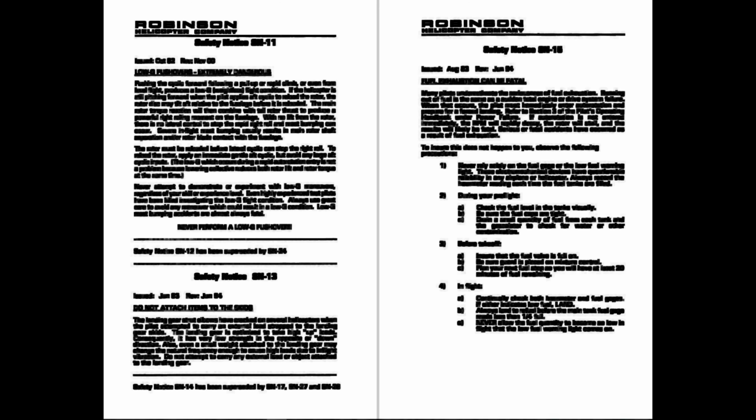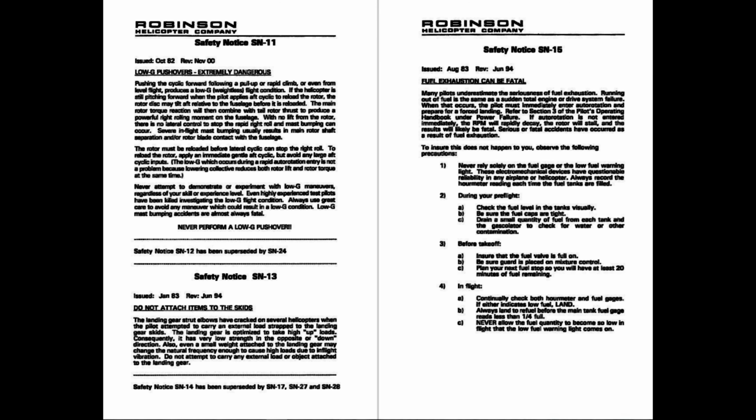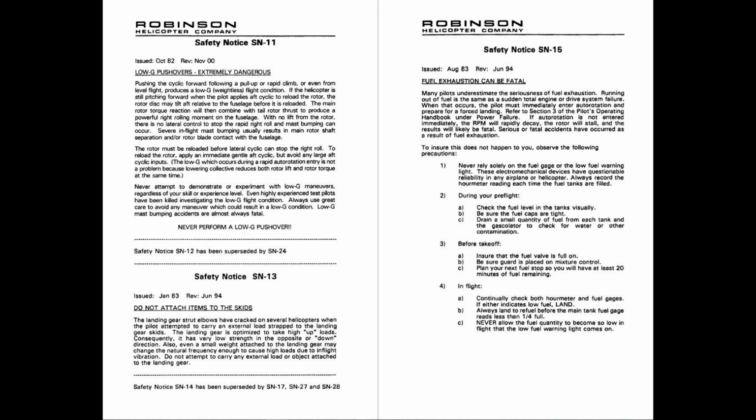If a low G situation is suspected, what should the pilot do? The pilot needs to reload the rotor disc before lateral cyclic will be effective. The way to do this is to apply immediate, gentle aft cyclic and avoid large aft cyclic inputs.